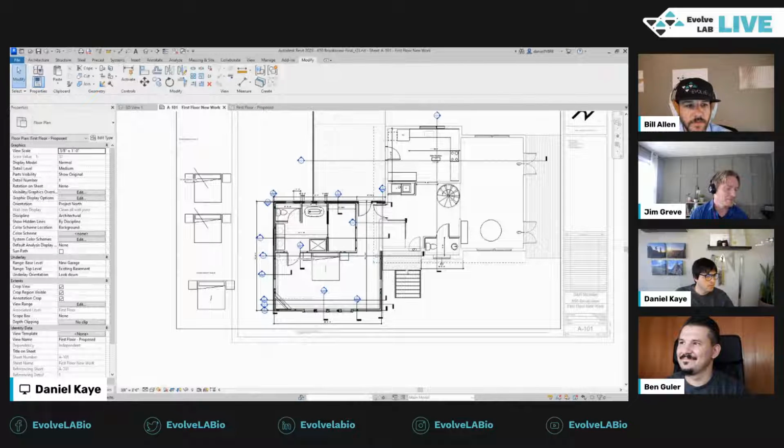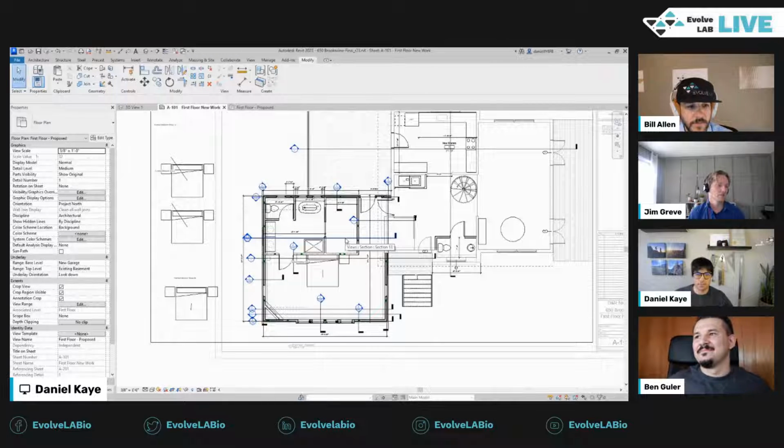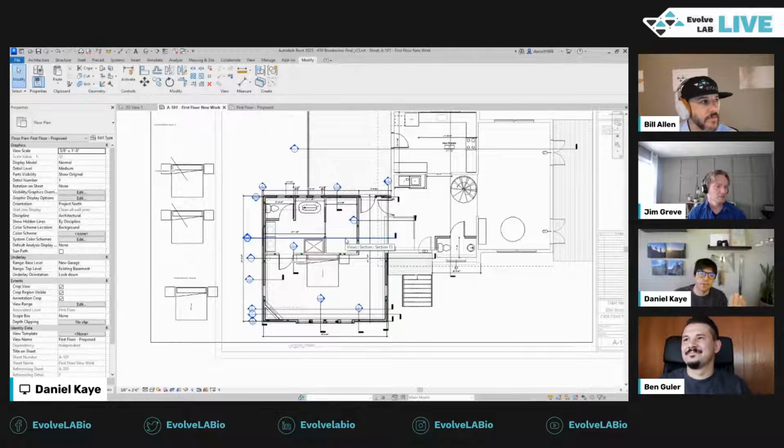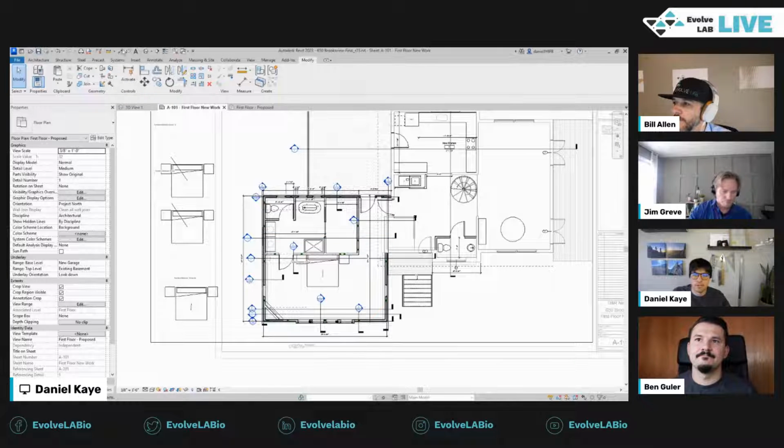Does it still snap to the center of the face? Yeah. Okay. When you make a connector by default, it's always the very center. So usually you'll make a surface or a little extrusion or whatever where the pipe or plug or duct connector actually models like the real shape you want it to be. Right. Instead of just a box like I did. I don't know, some people though, for diagrammatic ones, it's just a cylinder with a few connectors. Because that's all you need at certain stages.